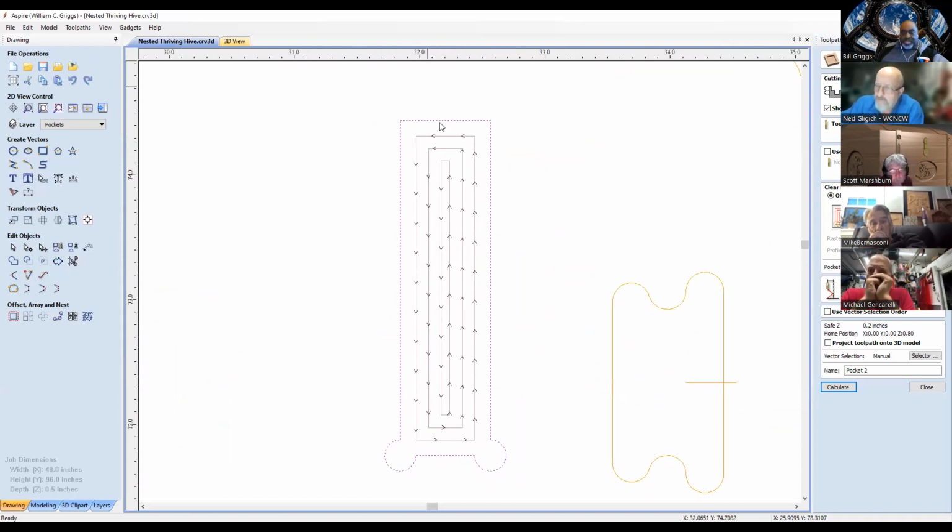There's a checkbox you have to press, which will turn it blue to show you where your toolpath is, inside or outside. Is that what you're going for? What I do, just to confirm that it is going correctly, is do 0.1 of an inch rather than 0.03. That way, it's a significant step that you can see. Okay, now do calculate.